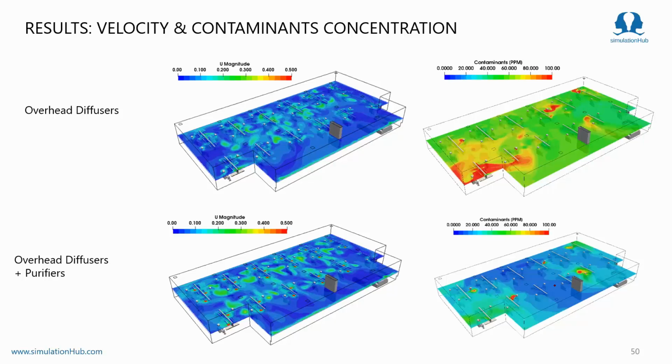So we can see over here that the contaminant concentration is now very low and almost identical to the UFAD system. In some sense you can say it is giving better results than UFAD as well, because this purifier is sucking the air from the local zone and purifying it. So we can say that in the vicinity of a mannequin, there will be contaminant-free air.